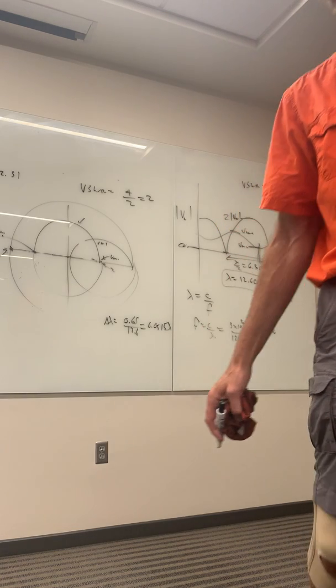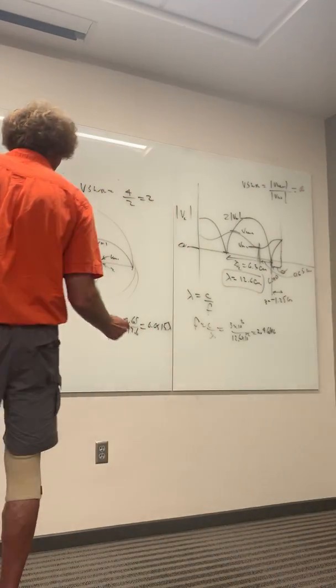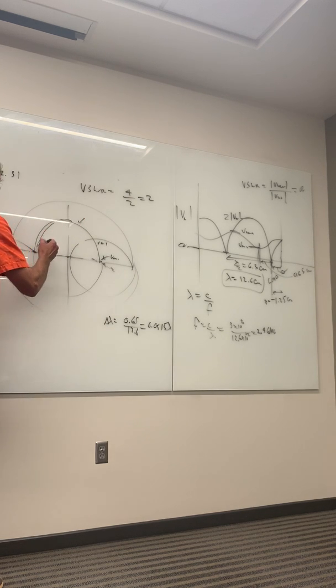All right. Now, here's the deal. With this particular one, I know that when I attach the load, the voltage minimum is away from where the load is. Do you follow me? It's towards the generator. I know this is the circle I'm operating on with the load. That I know from the visual, right? But I also know that that's where the actual Vmin will occur, right? But it doesn't occur there.